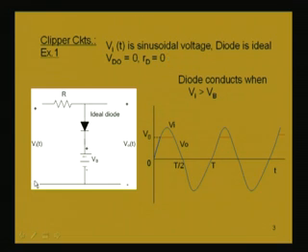The input applied to this circuit is, for example, a sinusoidal wave. The circuit has a resistance R and the diode, and at the end side of the diode is connected a battery, with its positive terminal to the N side, and this battery has a magnitude of VB, say.